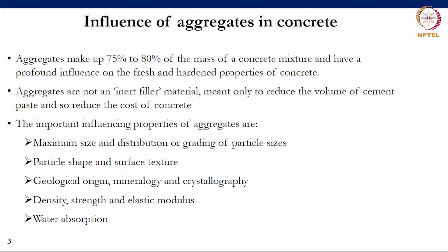A few of the important properties of aggregates that influence concrete behavior. Firstly, the maximum size and distribution of grading or of particle sizes. The particle shape and its surface texture. The geological origin, mineralogy and crystallography of the aggregate that is being used. The density, strength and elastic modulus of the aggregate itself. And then the water absorption properties of the aggregate. And as I go through this lecture, we'll cover and consider all of these aspects as we go along.